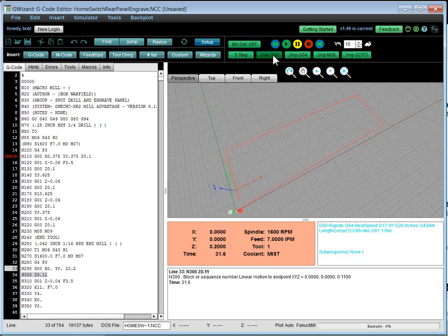So we're on the G00. Here's an interesting one: I can move ahead to the next dwell. Why in the world would you ever do that? The answer is, it's really easy to stick a dwell into a program you're debugging and use that as a marker for where you'd like to go over and over again. The dwell doesn't really change an awful lot in a program while you're simulating it. It doesn't change the backplot at all. So dwell is just a handy way to do that.